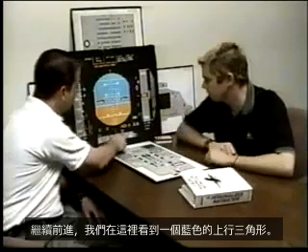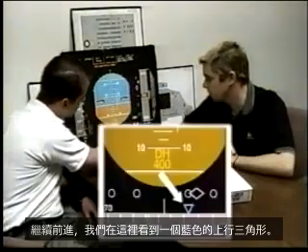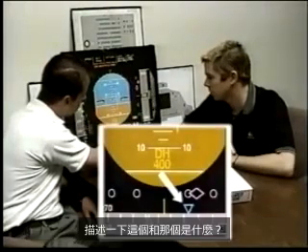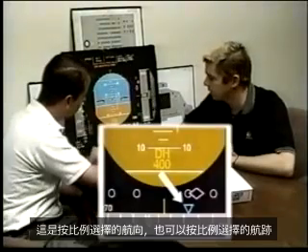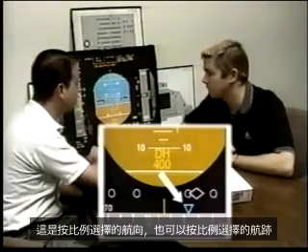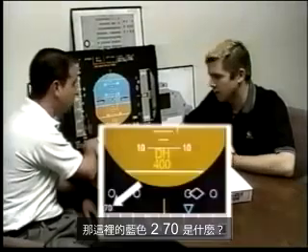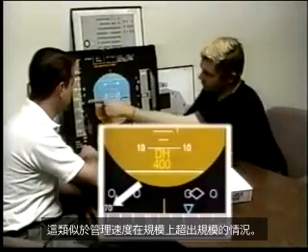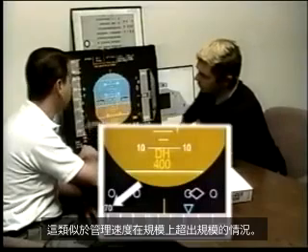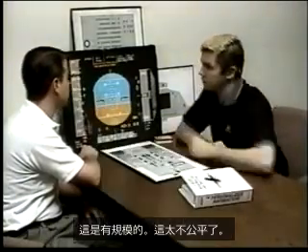Moving along, we have a blue upside down triangle here. Describe this to me. What is that? That's selected heading on scale, or could be selected track on scale if we selected that mode. Okay, and then what would be the blue 270 here? It's the same thing, but it's off scale. It's similar to the managed speed being on scale, off scale. This is an on scale, this is an off scale.